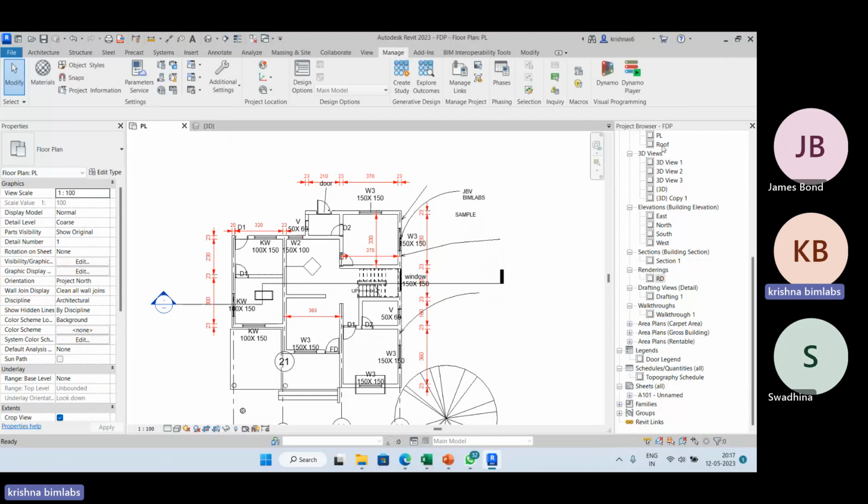Okay. So the R value and U value are important to know in order to do the energy analysis of the model. And before doing the energy analysis, we want to know the material study of this particular model. If the value is higher, or if you want to change it, you can just adjust it, but if that adjustment is not enough, then we have to change the material also.